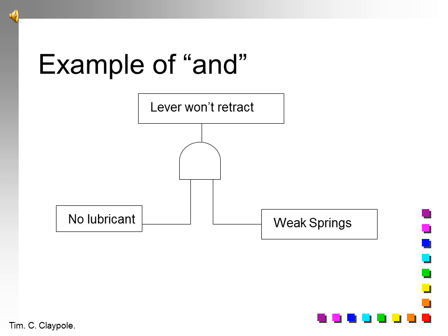So, what have we looked at? We have looked at failure mode and effect analysis. This is where we look at the failure of individual components and how they impact on the performance of the design. We've done it for processes and we've done it for the design itself. And now we've looked at fault tree analysis. This looks at the undesirable event and looks at how you can add the statistics together to make an estimate of whether the undesirable event will occur.